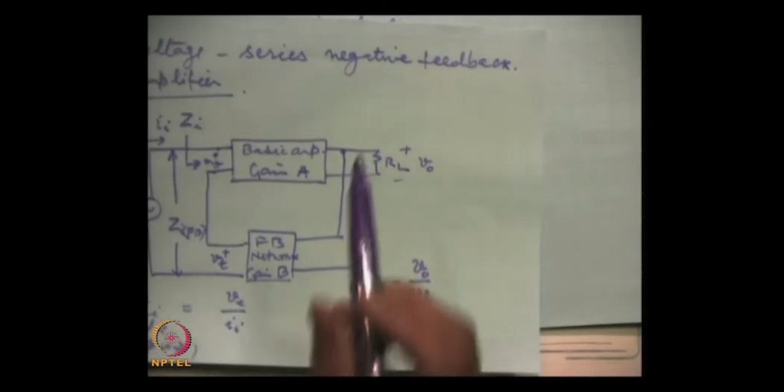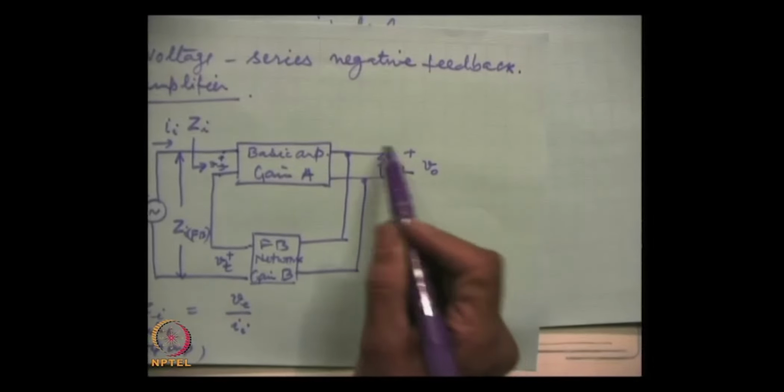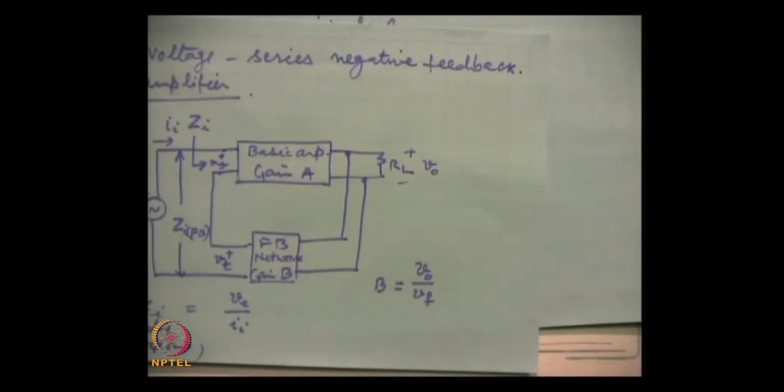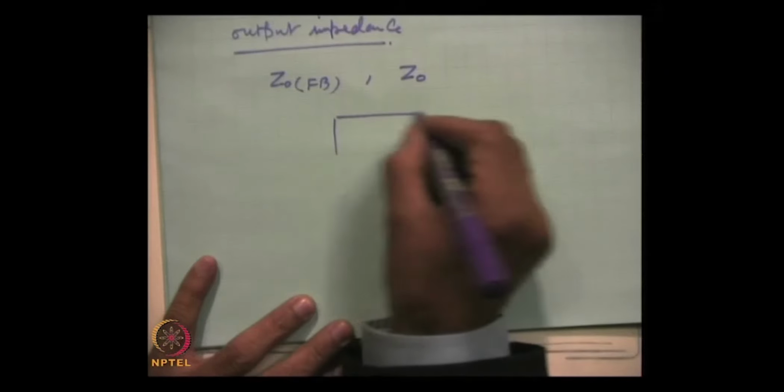The first thing which we will have to do is we have to remove this load resistance. Load resistance is not included. This is the general principle of the analysis, that when output impedance is to be taken, take out that resistance and connect a voltage source Vx. When we do that, we will observe the corresponding current Ix. So, what we are talking about is this.